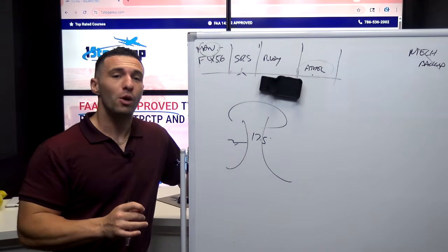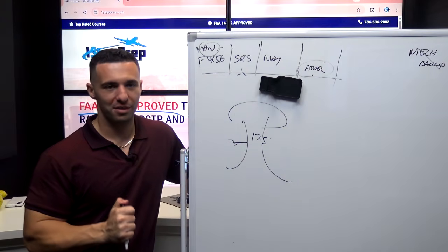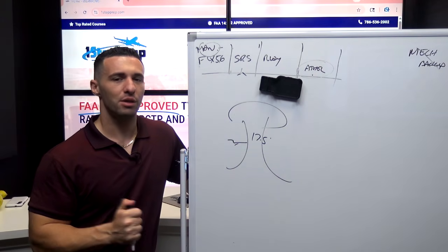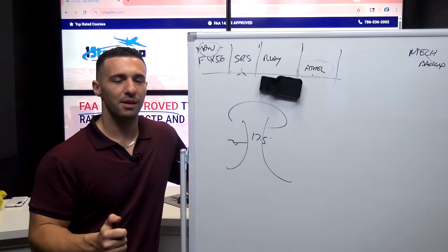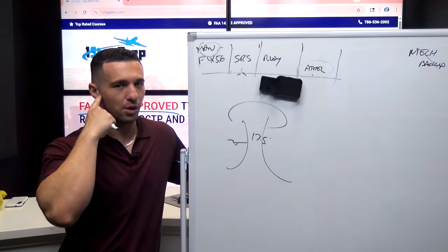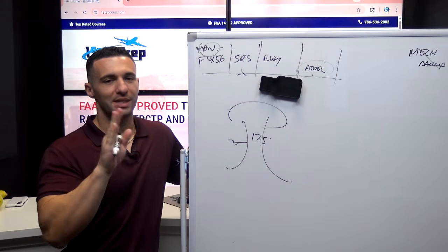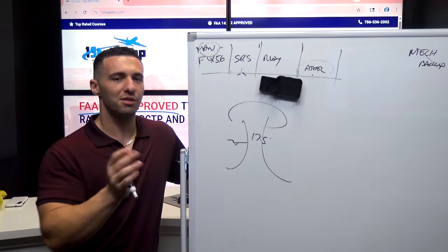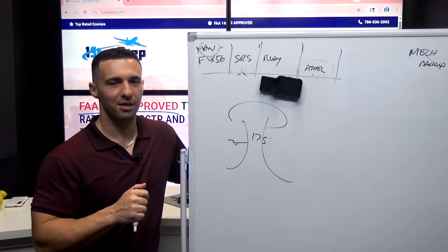So that's the first thing. That's why we're looking at the radio altitude, because it's very possible that the altimeter will show an erroneous climb or descent. And the other thing you'll notice is there's no mention of airspeed. So we don't say airspeed's low, airspeed's high. We don't say anything like that, because if you do hear speed is low, the tendency might be to lower the nose. And the only way to win the shear really is through angle of attack. So we're reliant on the protections to do what they need to do and allow us to just fly with aft side stick as needed to fight the shear.